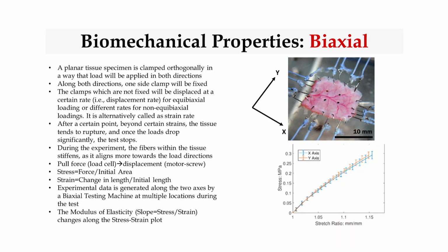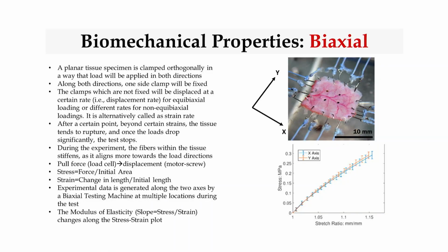So we have also developed a few machines in our lab, because they would all cost like 40 to 50 lakhs or so, like in the Indian system. So it's better to develop one, it's much easier to use, right? We have developed a machine which costs us less than 50 or 60,000 rupees, and that was really valuable in doing the biaxial tests. And after that you find out the modulus of elasticity, which is again along the two different directions. So you will have a separate x direction modulus and a separate y direction modulus, right?